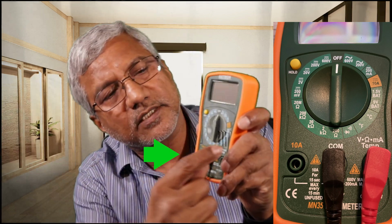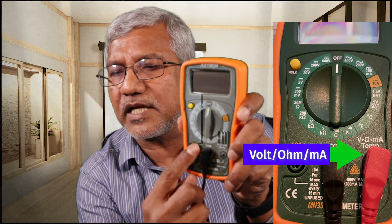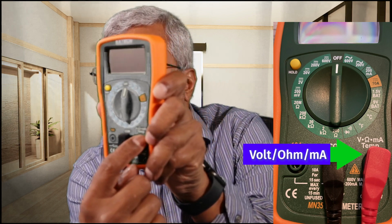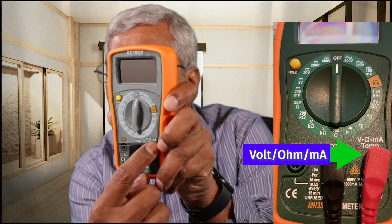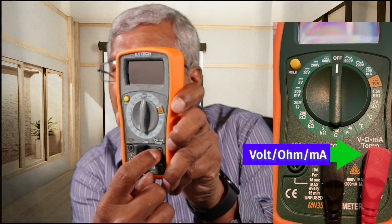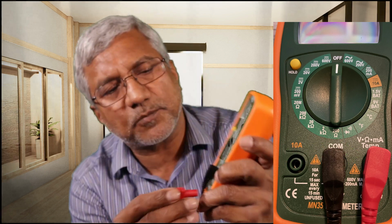And the red has two positions. It can go to either here or on the other side. Most of the time we'll use it here because, as you can see, this is where you put it when you want to measure voltage, resistance, and very small currents like milliamperes, or even when you're measuring temperatures. So let's put it here.